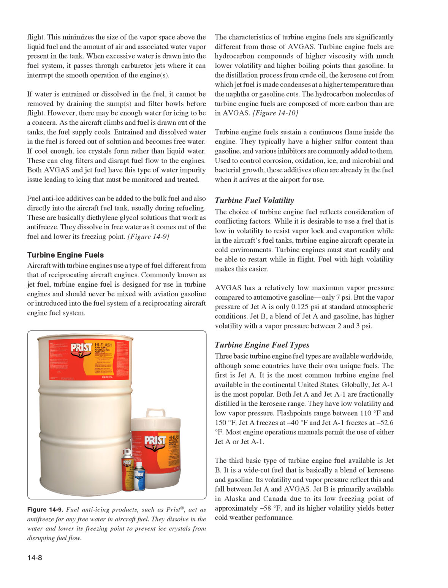However, there may be enough water for icing to be a concern. As the aircraft climbs and fuel is drawn out of the tanks, the fuel supply cools. Entrained and dissolved water in the fuel is forced out of solution and becomes free water. If cool enough, ice crystals form rather than liquid water. These can clog filters and disrupt fuel flow to the engines.